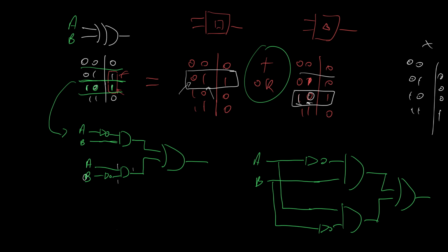So in this way, we can write any truth table we're given in a sum of products form. The products, together with inverters here, allow us to pull out individual rows that produce a 1 at the output, and then we simply OR them all together to get the desired truth table that we want.